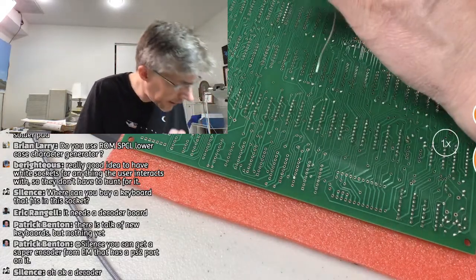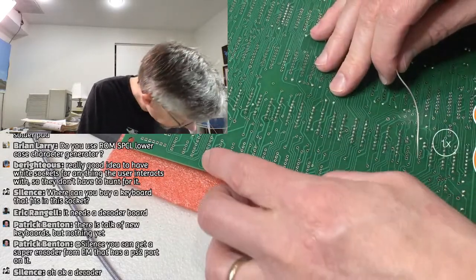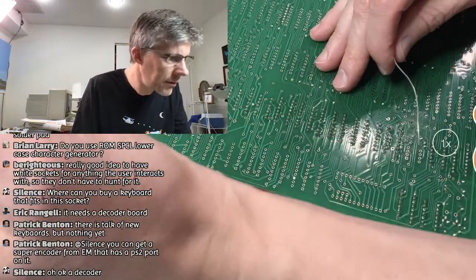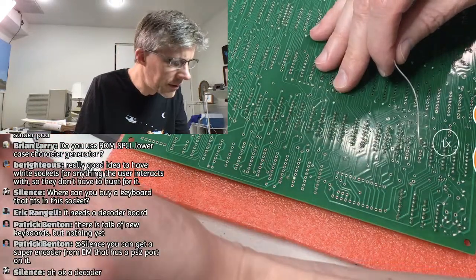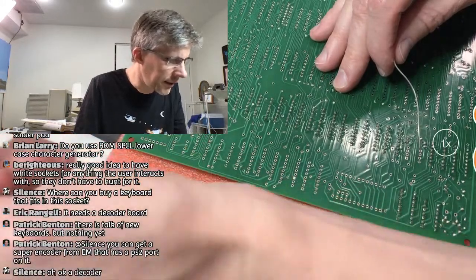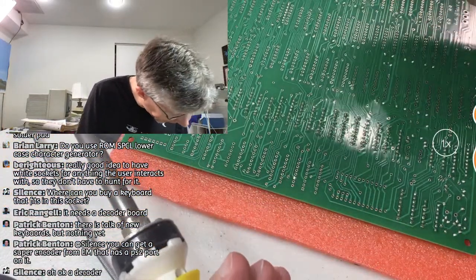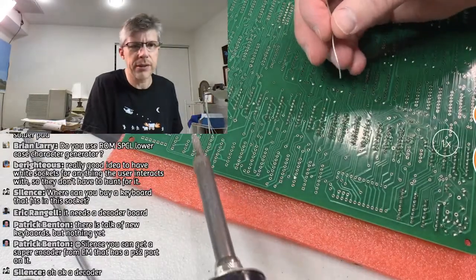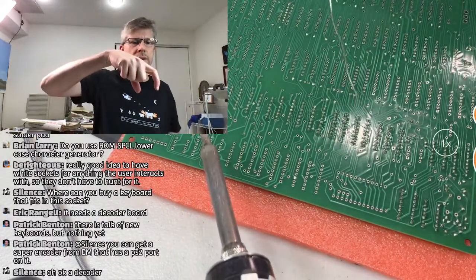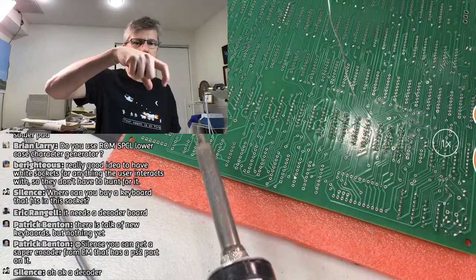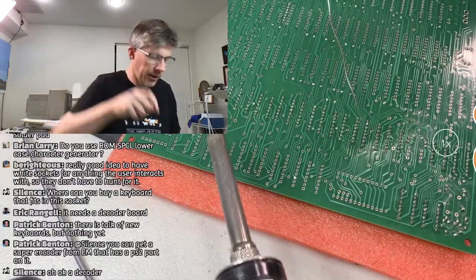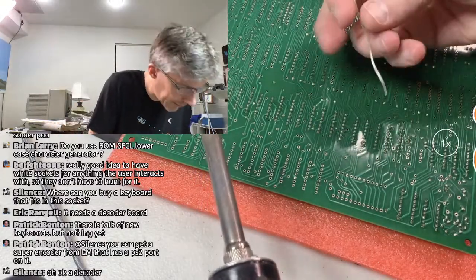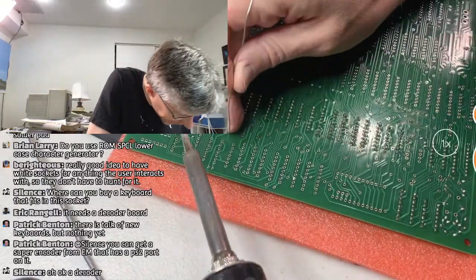So let's go ahead and we'll solder these in. I think I need to get a new brass sponge or something. With sockets, I typically tack down opposite corners. So I'll tack down one pin and then the opposite pin in the opposite corner just to hold the chip in. And then I don't have to worry about it getting skewed as I'm soldering. So we'll go ahead and do that.